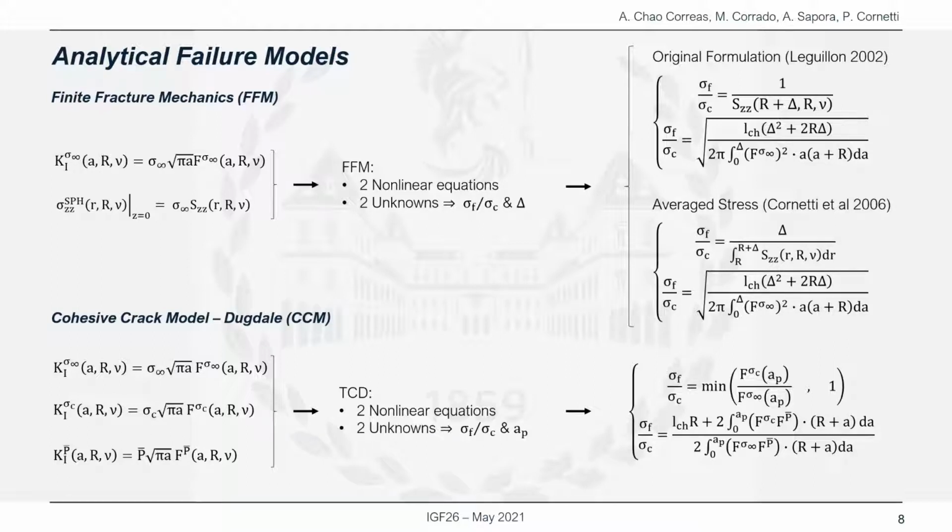The last stress intensity factor function can also be substituted by the crack mouth opening displacement if this expression is known. The minimum operator, in this latter cohesive crack model, simplifies the subsequent numerical resolution of the system by avoiding the divergence in a_p noticed by Cornetti and Sapora in 2019 for vanishing size of the defects, although in that later work they were dealing with penny-shaped cracks.